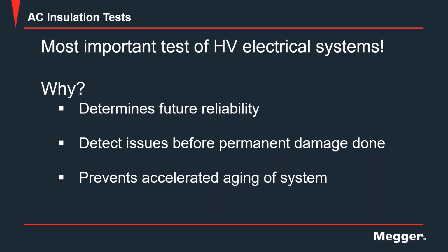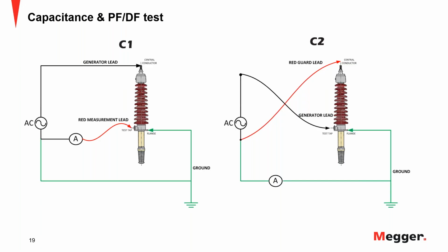And you can see on different reports that little parts from the explosion of a porcelain bushing will go as far as 100 yards, 150 yards away from the explosion. So it's very risky, especially if you have people in the substation walking from time to time, doing typical inspections or maintenance activities. So we have to be careful with this, and the more proactive we are with our bushings, the better we are with the safety and health of the system.